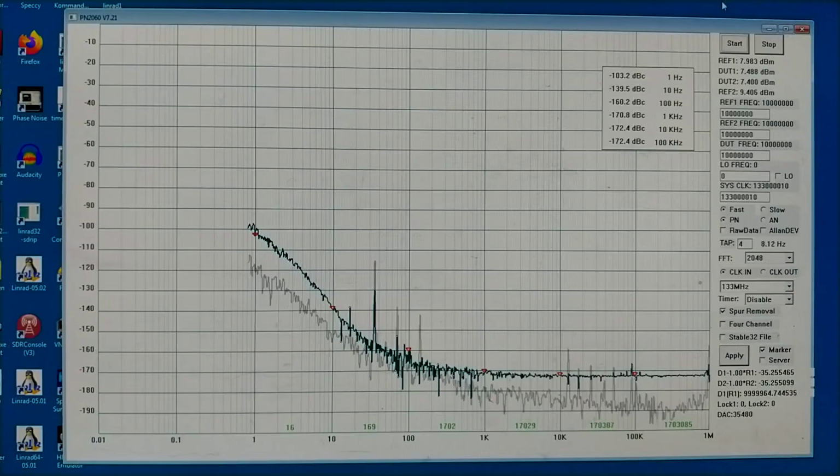I have applied feedback again, and now the oscillator is running with a new filter configuration. And the noise is very high now also. So I must conclude that the crystals themselves are far more noisy when operating with a large capacitor very close to the series resonance frequency.